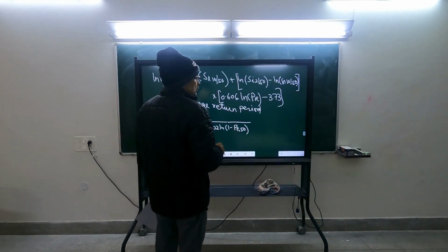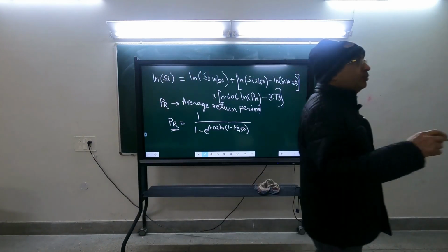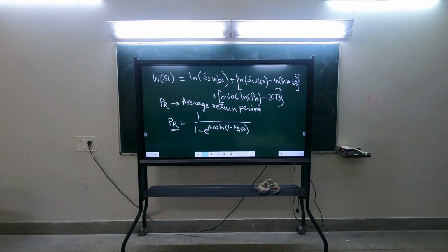That PR, suppose I want you to determine corresponding to 2% in 50 years. Sorry, 5% in 50 years. So DBE and MCE value is given. As per current code, it is half of 1.5 into Z by 2 is DBE and 1.5 Z is MCE. And if I ask you to calculate it for, let us say, SA 0.8. So at 0.8 second, you know the value of SA. Okay.